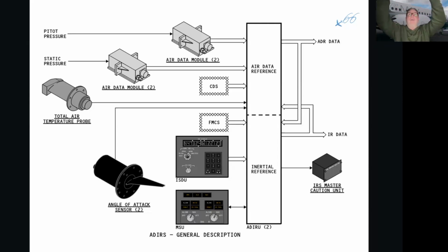On that post above it, usually there is the present position, the GPS present position, in terms of latitude and longitude, like this display here. So if the pilot wants to manually put the present position in when they first get on the aircraft, they only have to look up and copy what is above that guidance system. There are other ways which we'll look at in a minute.